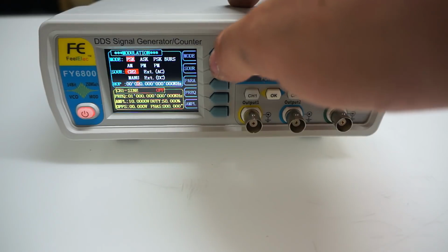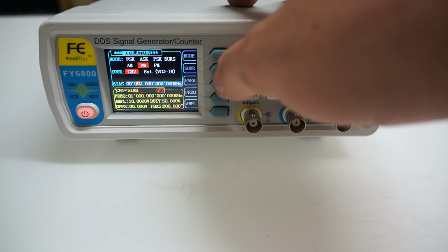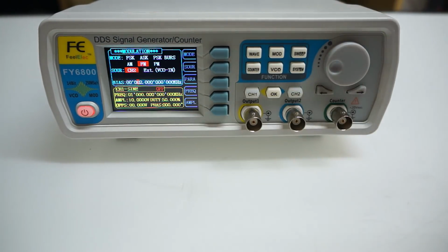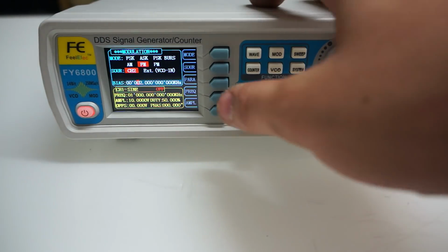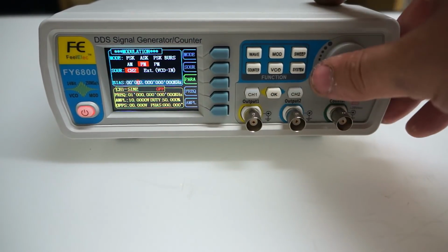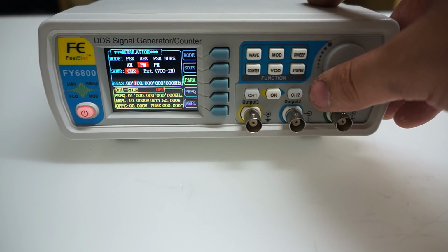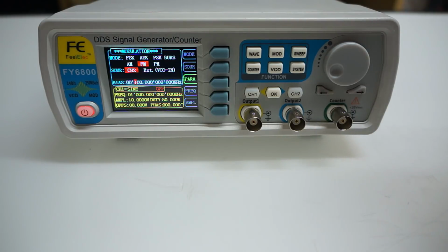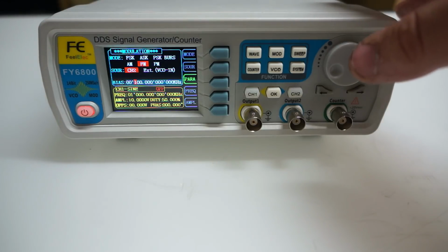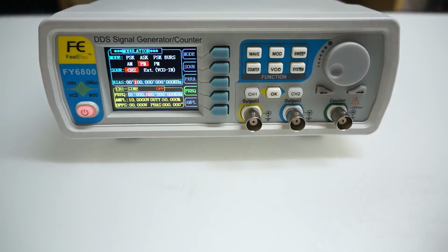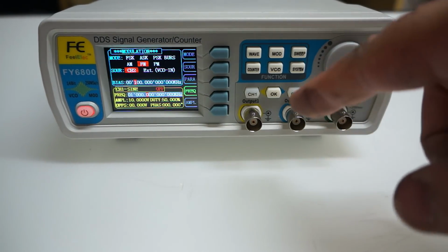Let's select frequency modulation. We press the modulation button a few times, and we can select the source, which is channel 2. Channel 2 now modulates channel 1 with a bias of 2 kHz. We can also change this to like 100 kHz. Now channel 1 is modulated with the frequency and waveform of channel 2 with a bias of 100 kHz. If you select frequency or amplitude, we can also change the frequency and amplitude of channel 1.